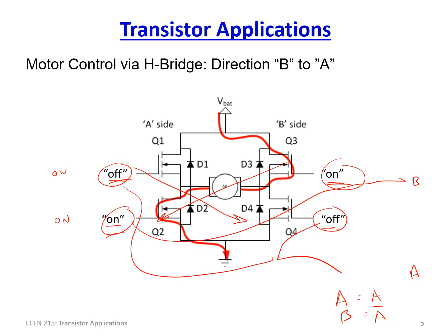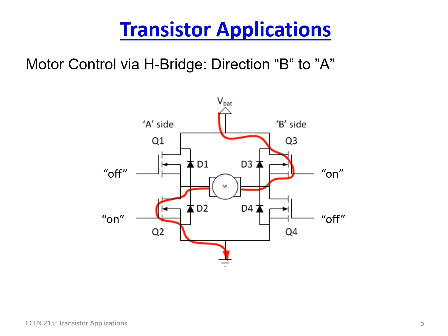There's some delay logic you also have to add, because even if you briefly short on, if these are on at the same time, you will short.